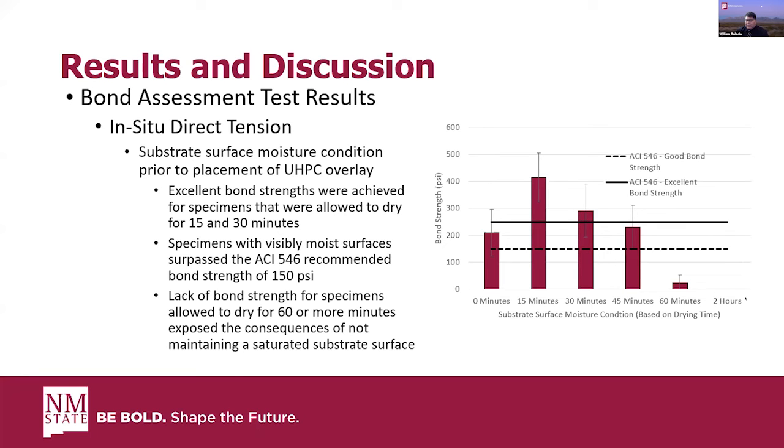And it should be noted that the specimen here for comparison is the exposed aggregate specimen. This is the ideal case, to have an exposed aggregate texture prior to UHPC overlay. However, by not maintaining saturated conditions, we didn't achieve any bond. So we got 0 bond strength for those ones.